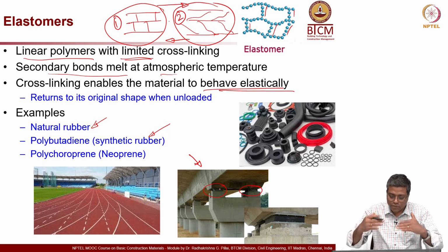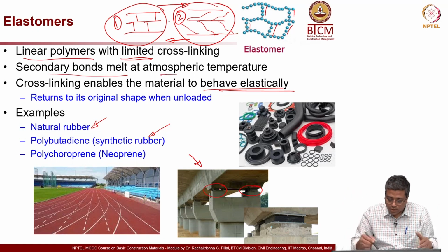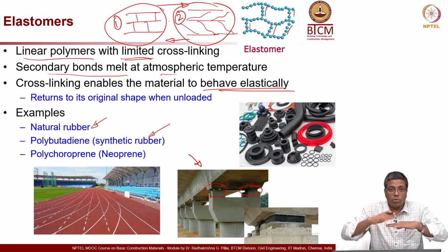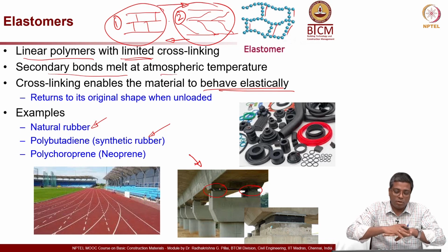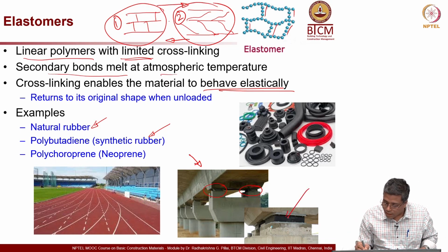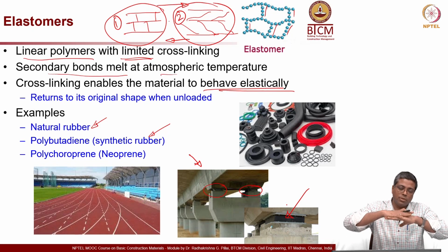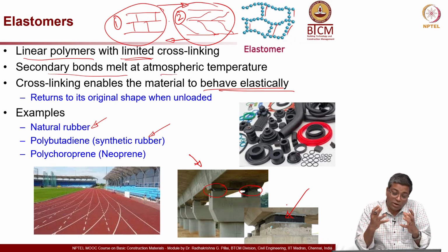The girder which is on the top, the actual bridge element, is resting on the columns or pillars. Where they are touching each other, that is where you provide a rubber or these neoprene pads. You can see this black piece here is what I am talking about. They put this neoprene pad so that there is proper load transfer happening, or like a shock absorber.